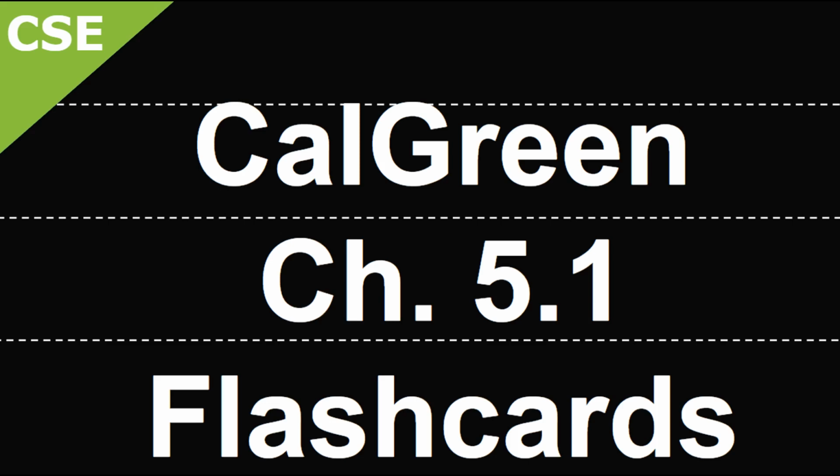As of July 2024, new updates for electric vehicle requirements for additions or alterations to existing buildings or parking facilities are as follows if it meets any one of these three. First, if construction work includes an increase in the power supply to an electric service panel as part of the parking facility addition or alteration. Or if a new photovoltaic system is installed covering existing parking structures. And finally, if an addition or alteration and the scope of work requires an increase in the power supply to electric service panels.